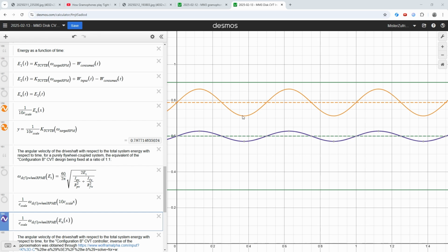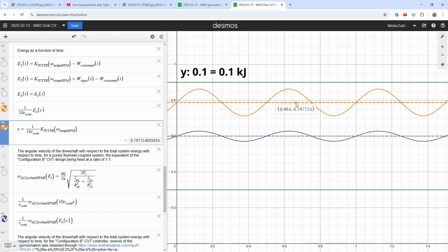First, we have the total energy in the system indicated by this orange curve. It starts off at around 788 joules, indicated by the dashed orange line, and is changing with a pedaling input. Here, I'm assuming that pedaling input is trying to achieve an average input of 75 watts, with 2 strokes, one for each leg, per second, countering a constant 75 watt load from the machine.